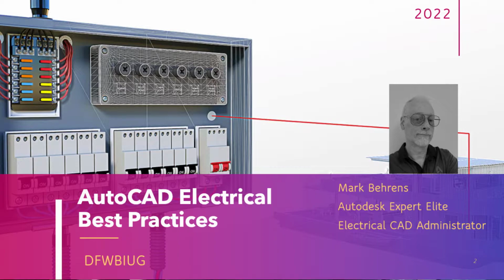Now, electrical requires a database that is correct and accurate. The issue that happens is when you work within normal AutoCAD and attempt to modify a block that's been done in AutoCAD Electrical. When you break that intelligence, you remove functionality, for example, from device 1 to device 2. Now, if I were to go to